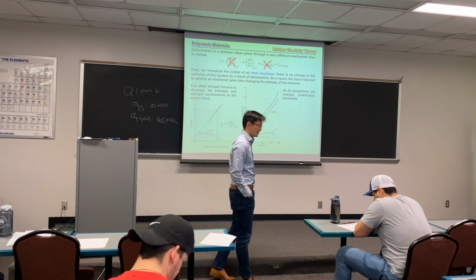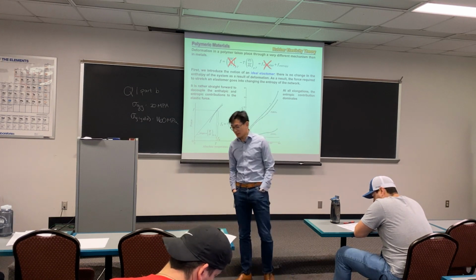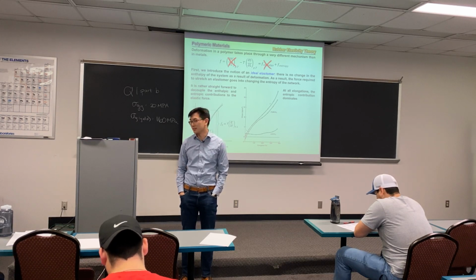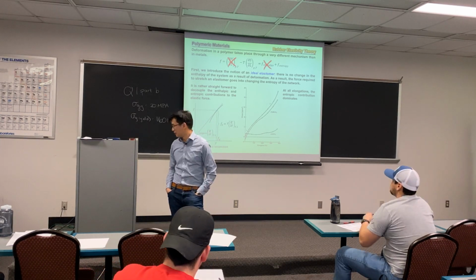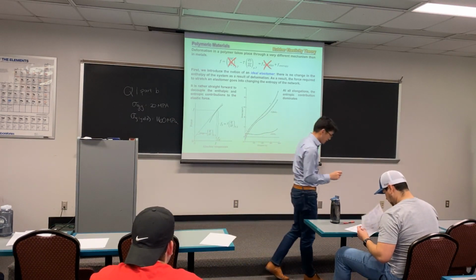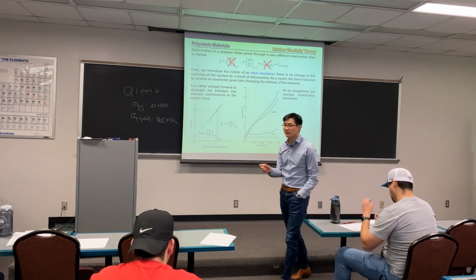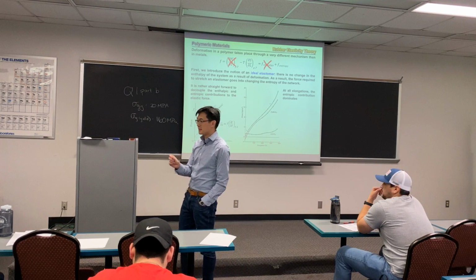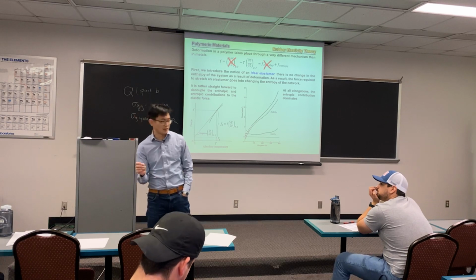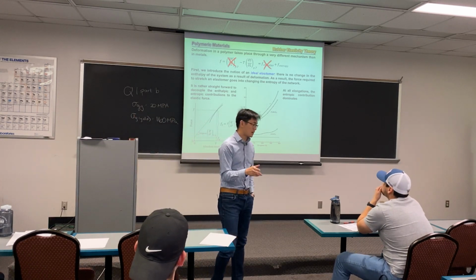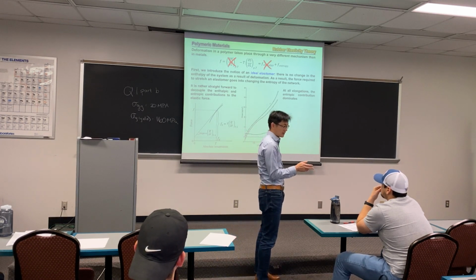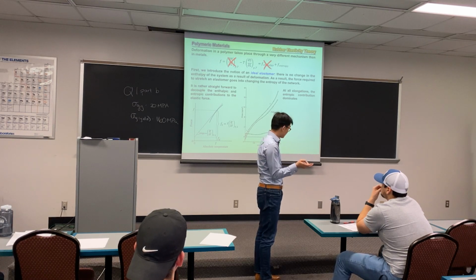Last lecture, we explained the difference between the energetic contribution and the entropic contribution to elasticity. We discussed how the spring in your ballpoint pen relies purely on the energetic interaction, where when you change the atomic distances between atoms in the crystal, they tend to relax back to their preferred location. That is responsible for this elasticity.